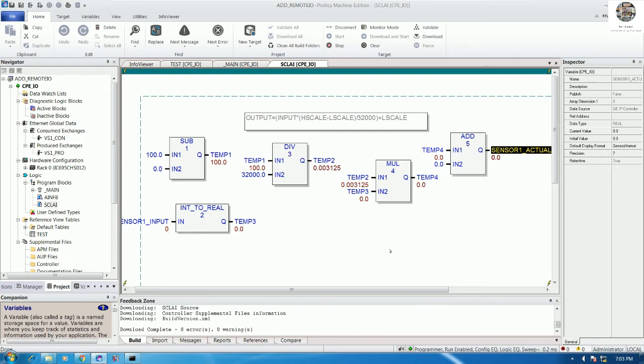Okay, so let me show the adjusting of the milliamp. Right now the milliamp is 4 milliamp, right? So if I adjust to 8 milliamp, let's see here around 24 degrees Celsius. Just one more. Yes, 12 milliamp around 49. Yes, it is the middle.